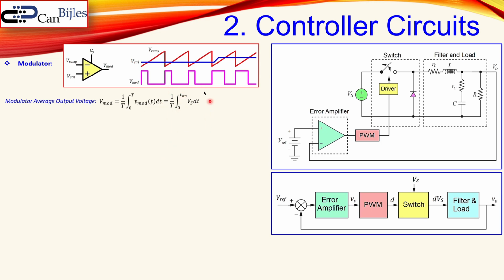This is actually the exact same expression as we have for the buck converter itself. But for the transfer function, we need to look at the change in the modulating signal divided by the change in the control, because the ramp signal is a constant change. The change here is dynamic, and the change in the modulation is also dynamic.